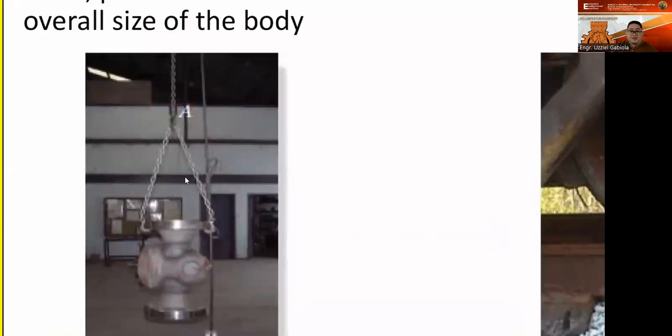Since these forces are meeting at the same point, our point A, no? So we have a tensile force there because it is being stretched, it has a weight here. The tendency is to load this weight, then distribute the weight here, and this single chain carries alone the weight that these two chains are carrying. Okay? So we can assume that the hook represents a particle, because its size is negligible compared to the weight we are considering.